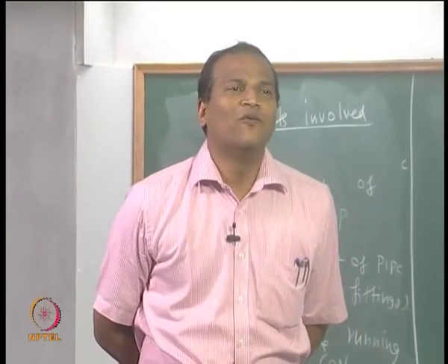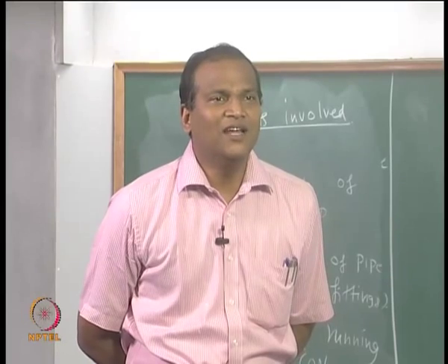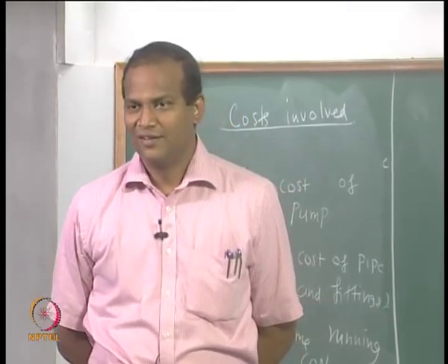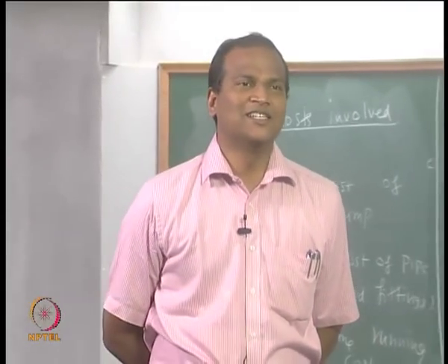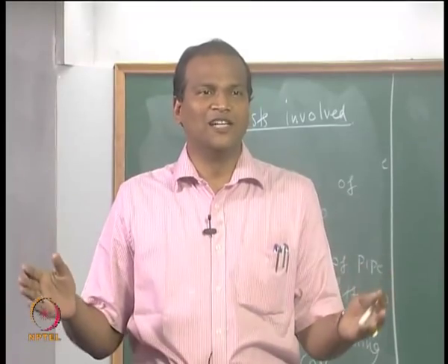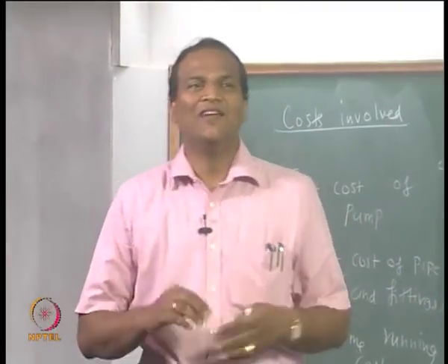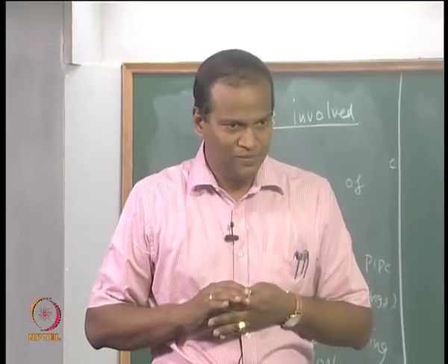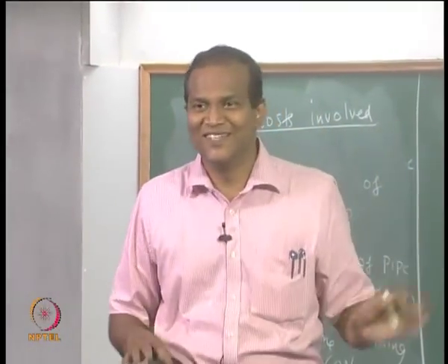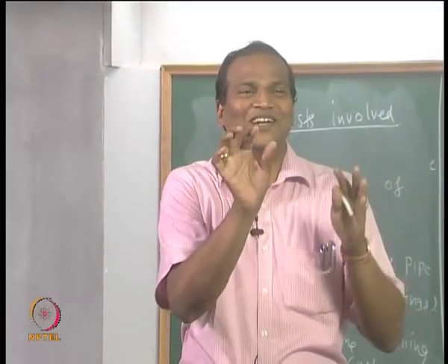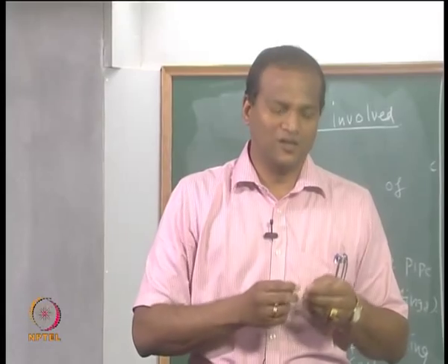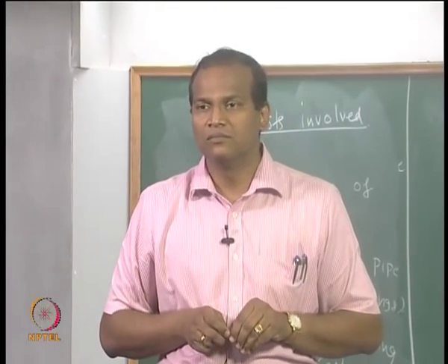So the weight is equal to pi d t L, correct? Pi d t L, where t is the thickness, d is the diameter and L is the length. Assuming that we are not going to have designs varying from 1 HP to 200 HP, if t is considered more or less constant, which is a questionable assumption, but I am allowed to do all these assumptions. So if t is maintained constant and L is maintained constant, the cost is directly proportional to the diameter.